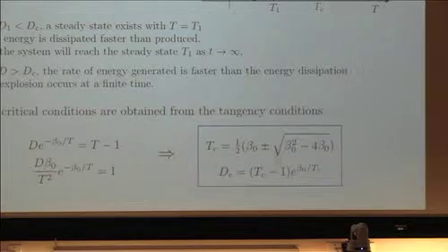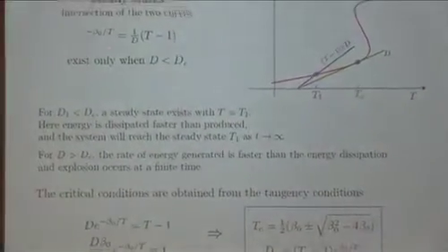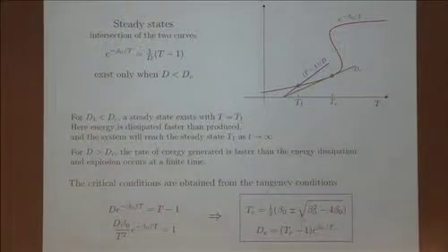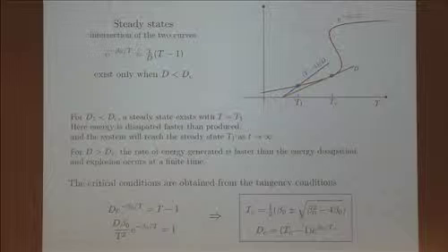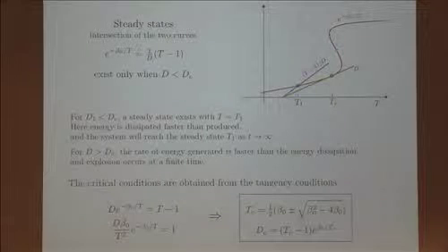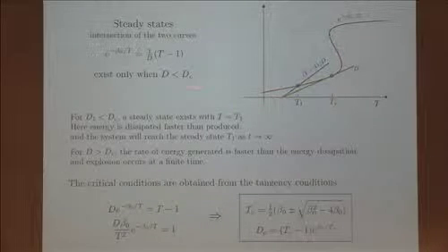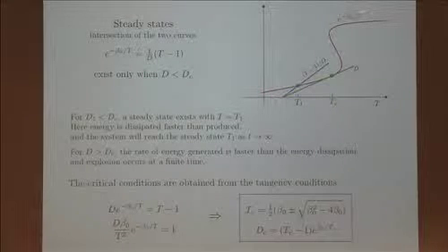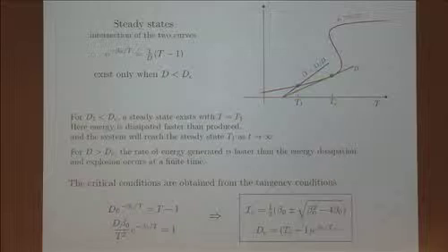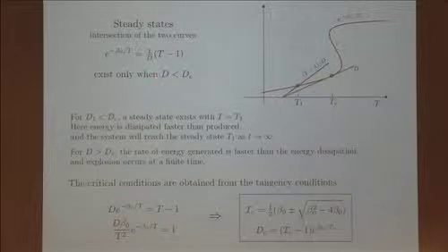In other words, here is the equation. What you do, you graph the left-hand side, you graph the right-hand side, and you find out where they intersect. The intersection indicates the point or the place where they are both satisfied, which is indeed the solution. So the left-hand side, this exponential, is here. It's the red curve. And the right-hand side is a straight line. So we plot them versus temperature, right? Because we are asking what is the temperature when equilibrium occurs. So the right-hand side is a straight line, but the straight line depends on 1 over d, which is this Dam-Kohler number, which is the slope of the line, right?